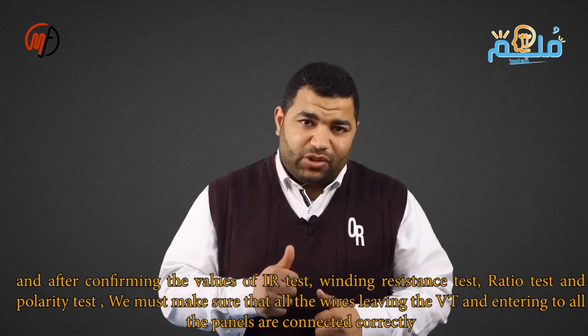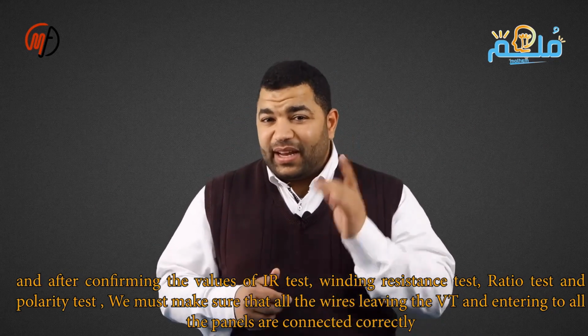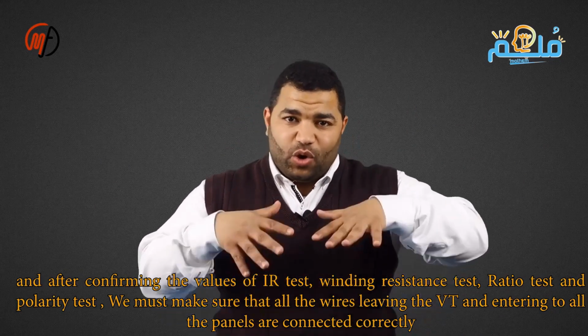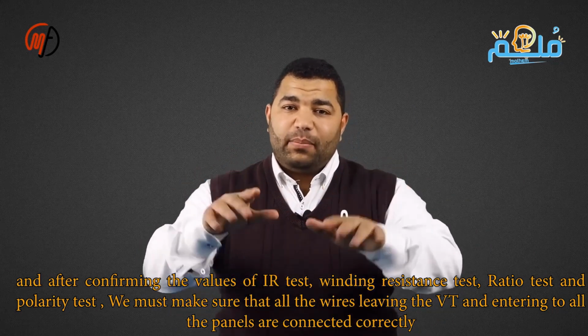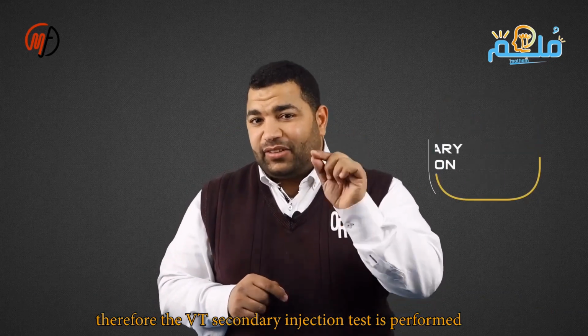After confirming the values from the IR test, winding resistance test, ratio test, and polarity test, we need to ensure that all the wires coming from the VT to all the panels are connected correctly. Then we perform the VT secondary injection test.